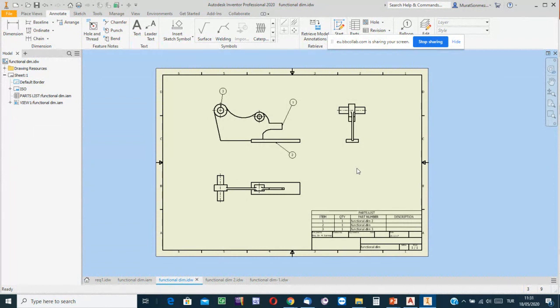So in civil engineering and architectural applications, we show the nominal values and do not think about tolerance, because the tolerance is in the order of a few centimeters, not a thousandth of 1 millimeter, but a few centimeters. In civil engineering, this part of the course content is not so important. Just know the dimension format and be able to show the dimensions correctly, without focusing attention on the upper limit and lower limit. But in the other branches of engineering, the upper and lower limits are quite important.